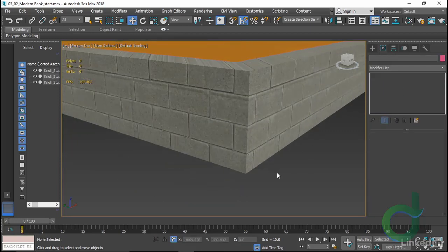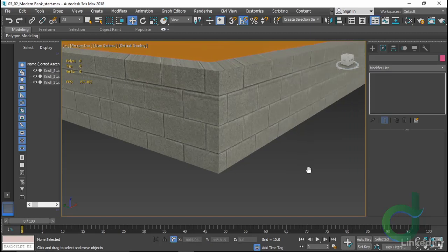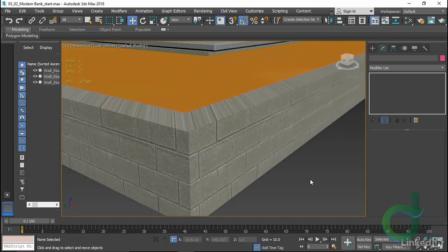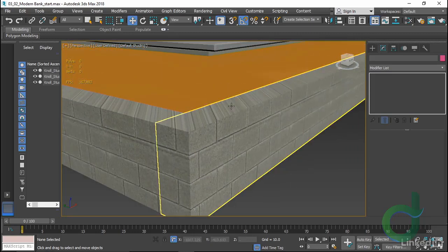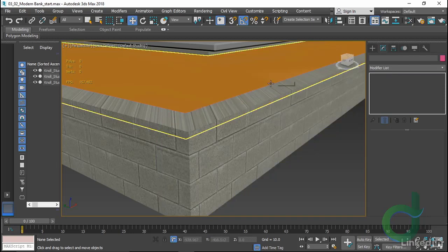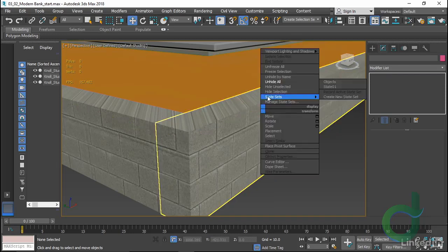Now what I've got, excluding the top, is that this texture spans cleanly around the wall as if this wall was built contiguously, which it would be. It looks like it was built with maybe 6-inch thick blocks instead of the full 8s. Then we can pay attention to the top. We've got some options here. We could hit them with a generic concrete material as a cap. We could make cap geometry, or we could change the texture on here and map it straight down.